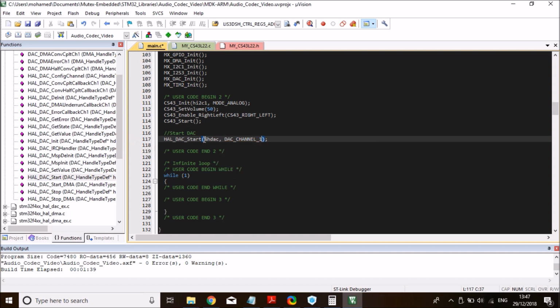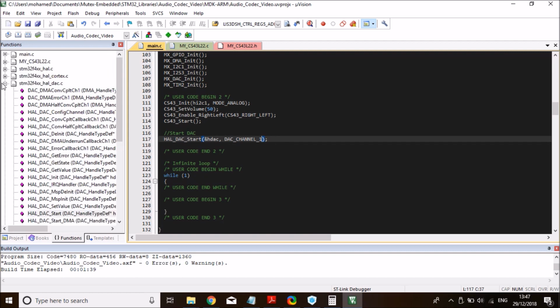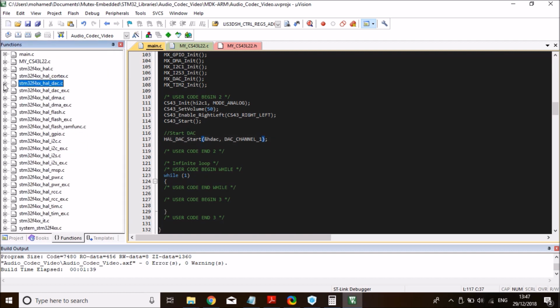And that's it. Now we need to define the timer interrupt callback that is going to sample at 50 kilohertz. By the way, I haven't explained a lot about this analog method. This analog output method is quite useful if you are streaming audio data sample by sample, and that's why I'm using the timer interrupt that interrupts at a 50 kilohertz sampling rate. It's quite useful if you have a processing algorithm where you're doing real-time processing and output to the audio.